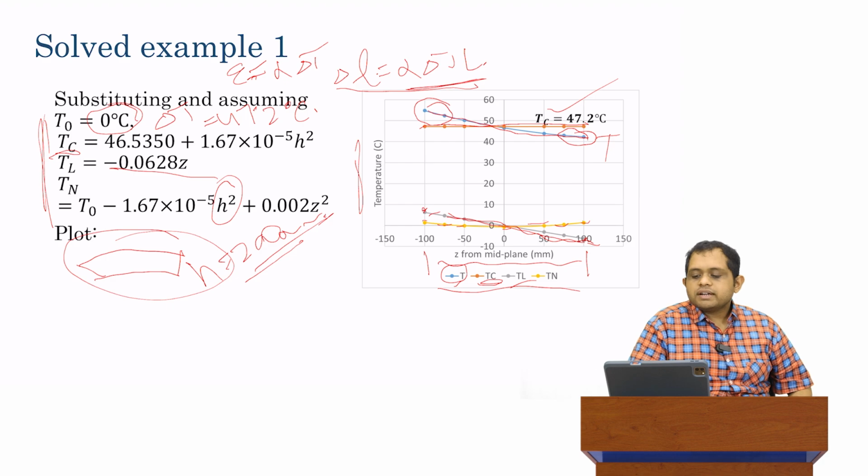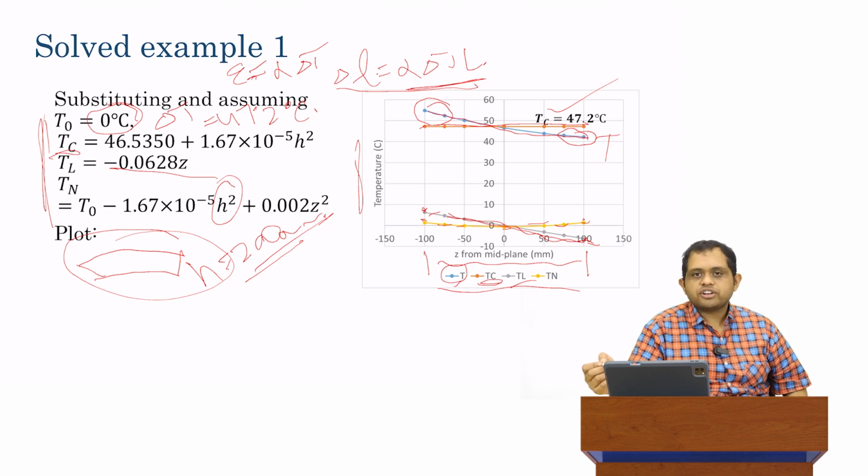What you will notice is that it actually has a positive value on either end. It looks like it is 0 at the origin, but at the midplane, it's not actually 0. It's a small value, and when we do our calculations for stress, it's not going to be a negligible stress, but it will be a small stress. So it's not 0 at z is equal to 0. It's just a small value at z is equal to 0, and it has a small negative value, I should add, and then it happens to have some positive value at z is equal to plus or minus 100.